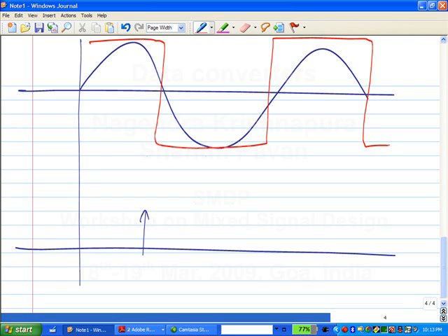nF0. Exactly, right? You will get the fundamental and all the harmonics. It doesn't look like that, but you get something at F0. And in this case, if it is symmetric, you will not get something at 2F0. But in general, you may get that also. You will get 3F0, 5F0 and so on. That's all, right? You have a periodic signal. Any periodic signal can be represented like this. All you get will be impulses at the harmonic frequencies.